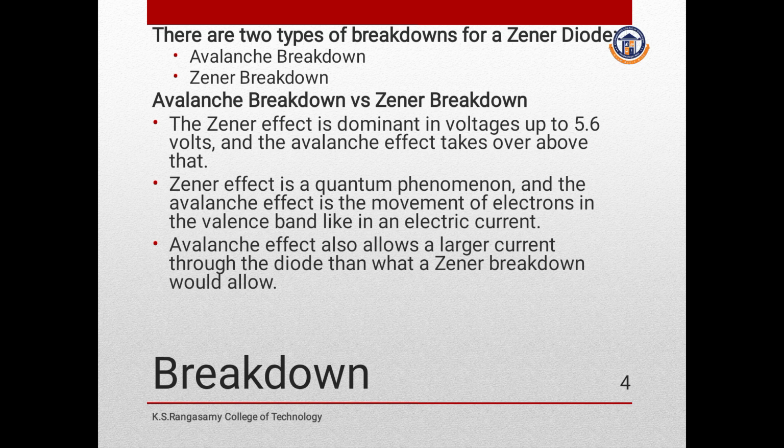When the value of the reverse voltage applied to the PN junction diode is very high, there will be a free electron. That free electron will gain sufficient energy, accelerate itself and move to higher velocities, and these high velocity electrons will collide with other atoms, so that the atoms release more free electrons, and the released free electrons again bombard other atoms.